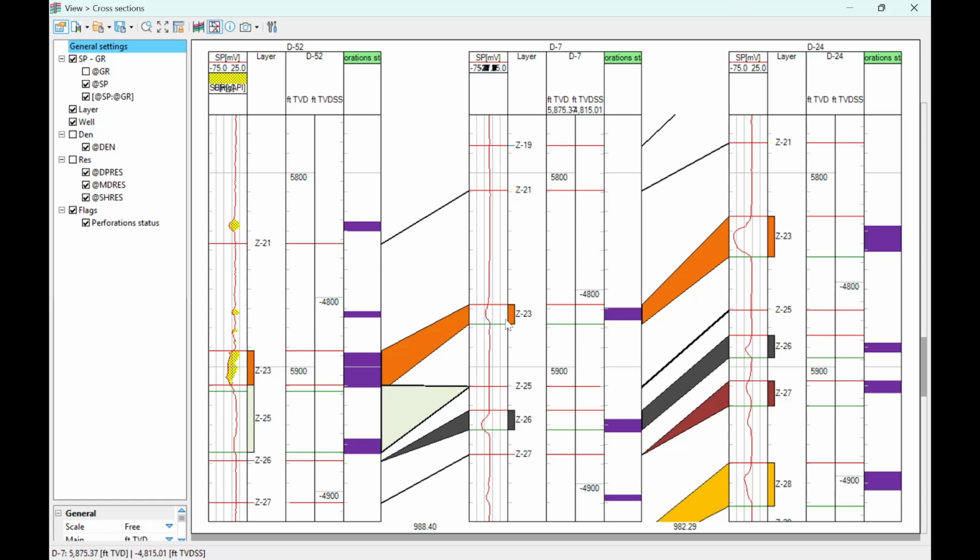The issue is that when we save this, the petrophysical data is not automatically calculated. The only petrophysical data that is calculated is top and base, but for example gross thickness, net thickness, porosity, all of this petrophysical data is not calculated automatically, so we will need to do that in the petrophysical data window. First, we will check if these top and bases have been properly saved.